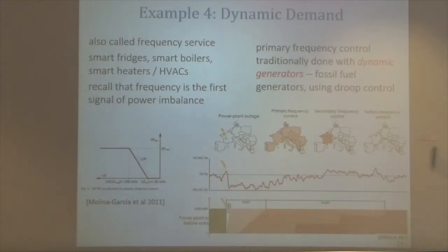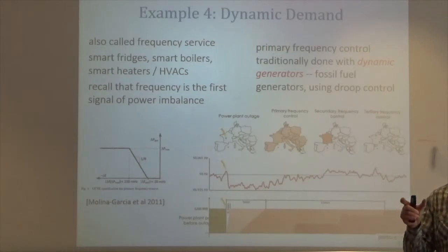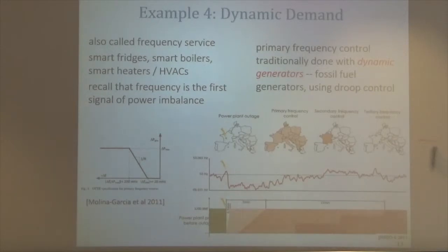The things we just discussed, like Voltalis, interruptible supply, are acting at periods of 15 minutes to an hour. So they're acting at the time scale of energy. There are other methods that try to act at much faster time scales, at the time scale of primary response. So I just mentioned the three time scales. This is an illustration that you find on the ENTSO-E documents. That shows what happens. This is an example of a nuclear plant being taken out of service unexpectedly in France.